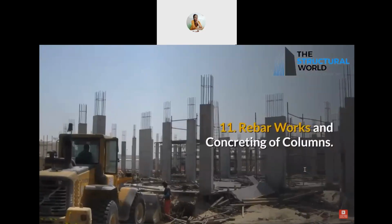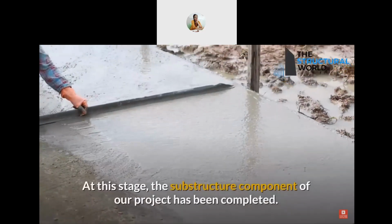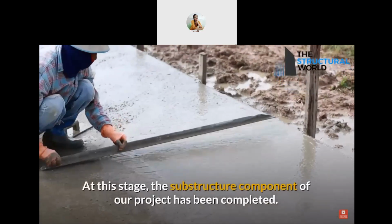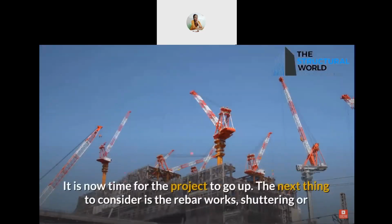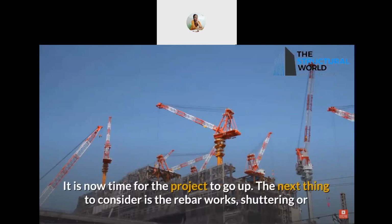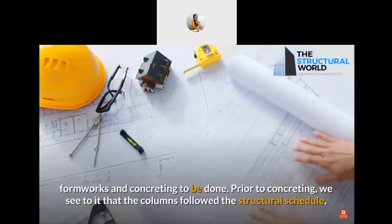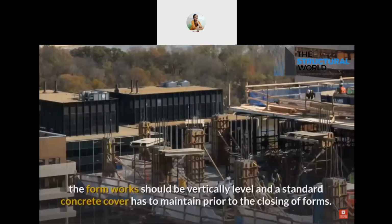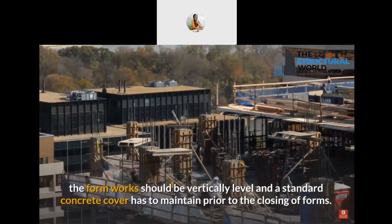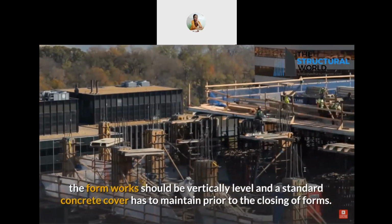11. Rebar works and concreting of columns. At this stage, the substructure component of our project has been completed. It is now time for the project to go up. The next thing to consider is the rebar works, shuttering or formworks, and concreting to be done. Prior to concreting, we see to it that the columns follow the structural schedule. The formworks should be vertically level and a standard concrete cover has to be maintained prior to the closing of forms.